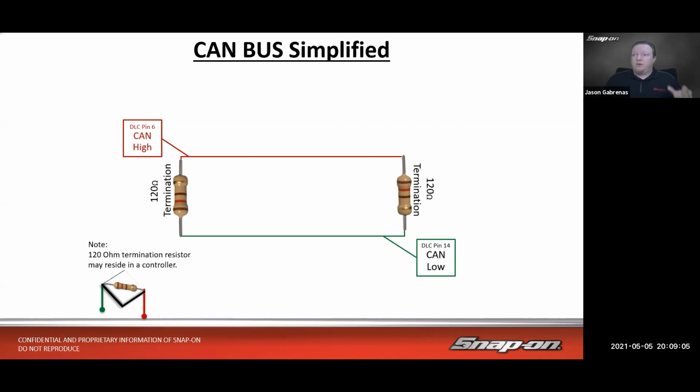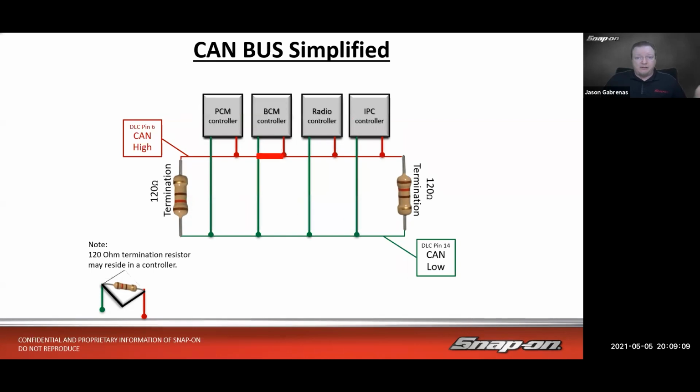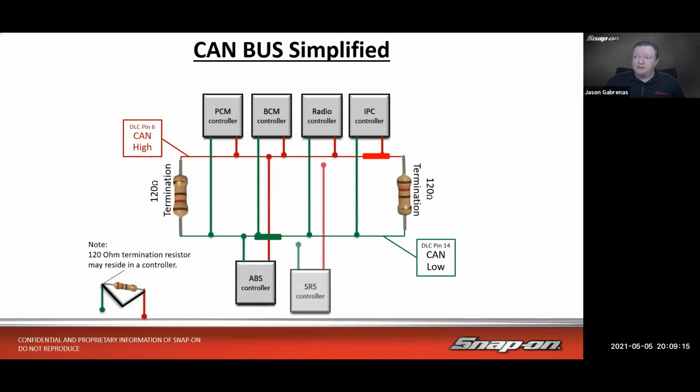One nice thing about CAN is it is modular. We can add some modules on there. They'll start communicating with each other once they're set up, of course. You want to add some more modules? Sure. Let's add some more modules. We can do that, and they'll still all communicate. They'll set themselves addresses on the network and start communicating.